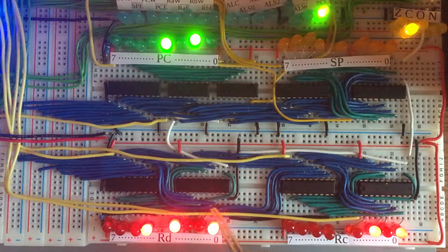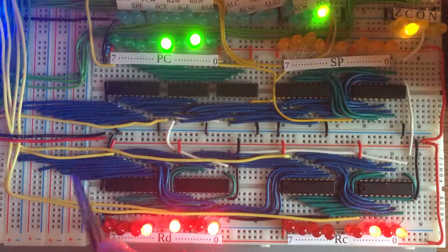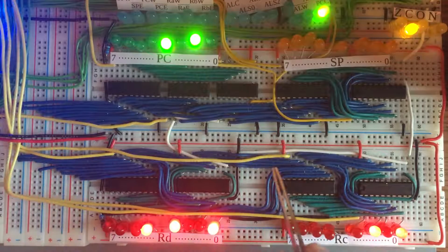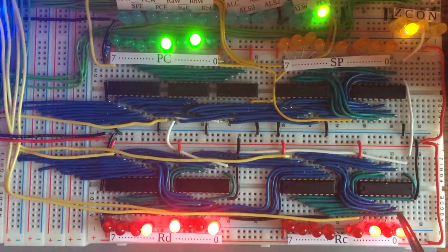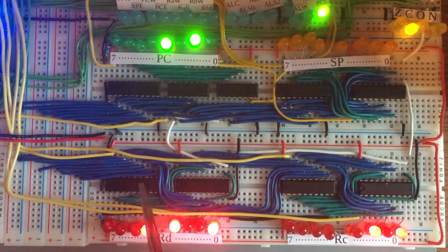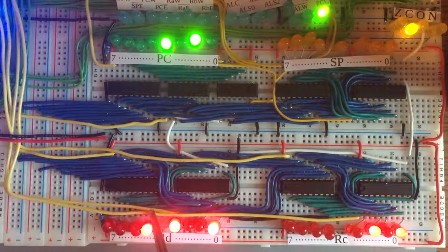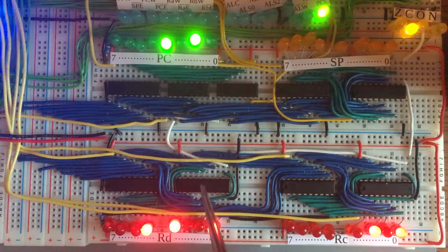And so they're connected to these blue wires, which are connected to those blue wires, so this is all basically just an extension of the bus, which is running all the way to here across these 2 registers. And so at several stages on the way, we're basically connecting to the bus. So we're connecting this buffer so we can output a value from the D register. We're connecting the actual register so we can input into the D register.